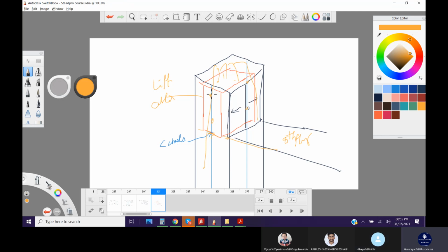These vibrations, this rolling, moving load will be given by our equipment vendor. If the moving load is given, it is fine. If not, normally he will say to apply some member load or point load on this channel location. Some load you will be giving, 5 kilonewton, 1 kilonewton, something like that. So again it's the input, how much loading is going to come in every location, while moving or while standing also. Whatever input he gives, we have to apply.